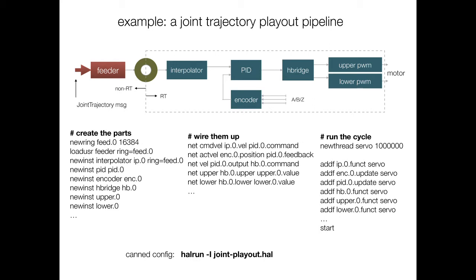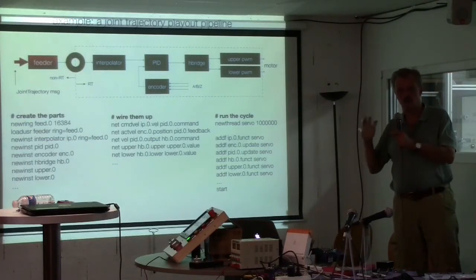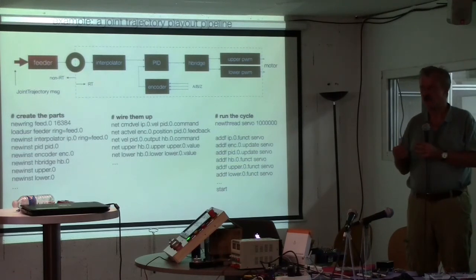You figure out the circuit which you need. You look up which components match my task, and most of them will be there. There are about 100 or so components, from very simple digital logic, analog logic, signal processing like low passes, high passes, differentiator, integrator, all standard fare which you'll learn at school, if you will.